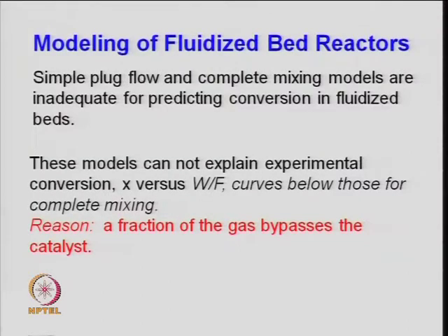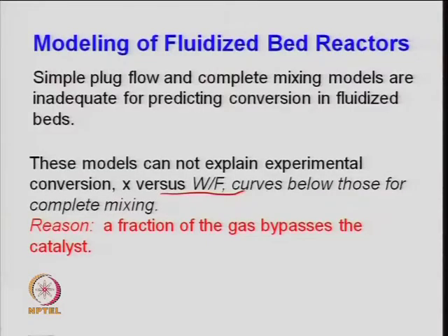Simple plug flow and complete mixing models may not be good to define the fluidized bed, because there is some kind of back mixing and some kind of plug flow condition. So, considering it exactly plug flow is not correct, and a completely back mixed reactor CSTR is also not correct, because there is a residence time distribution which lies between the plug flow and the CSTR, right.